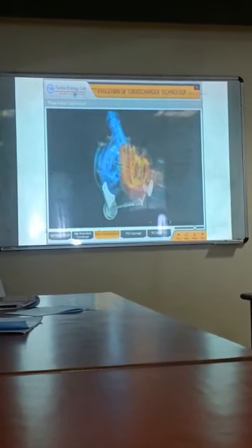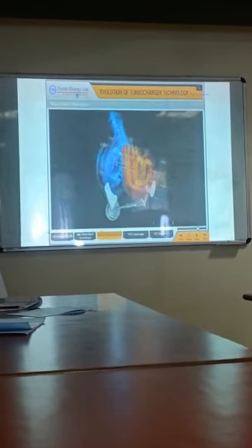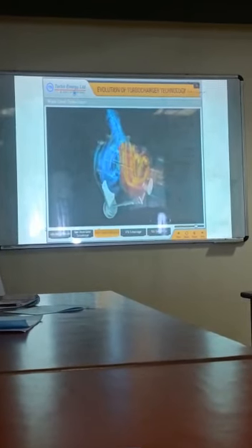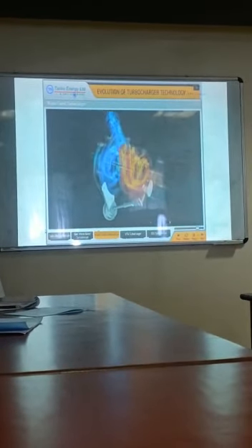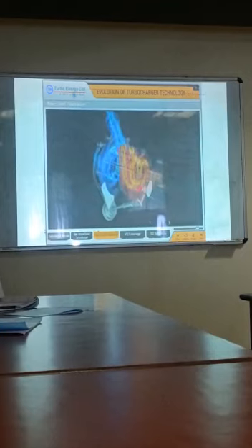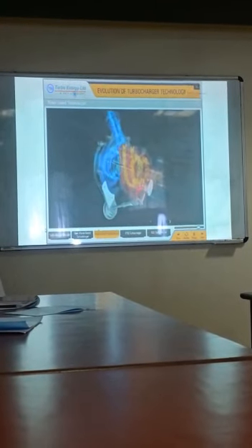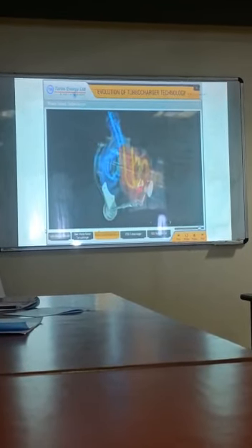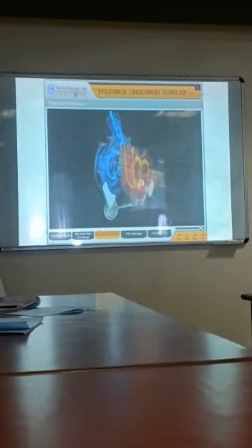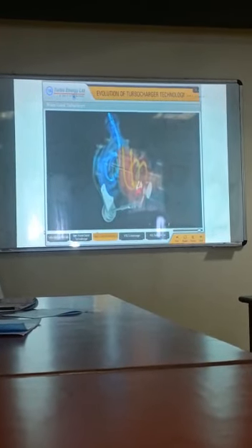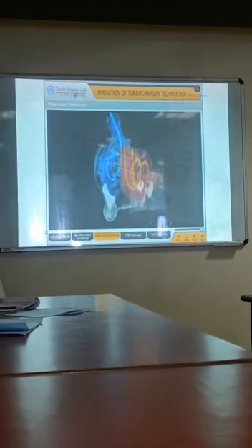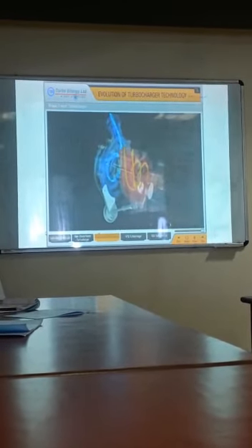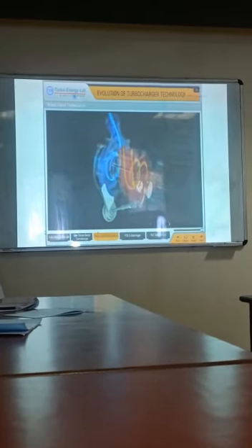The reduction in quantity of exhaust gases will result in a decrease of turbine wheel speed. Consequently, pressure in the compressor housing will be reduced. Since the air pressure is less, the diaphragm moves back to its original position due to spring pressure, and the wastegate flap assembly also comes back to its original closed position. Thus, the maximum boost pressure developed is always limited to the set value determined by the engine manufacturer.